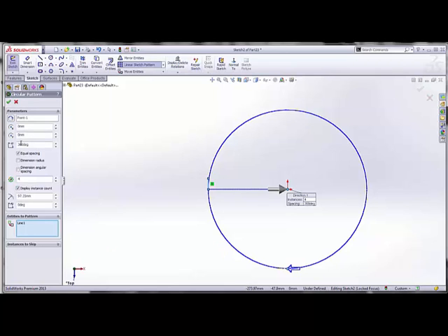As you can see, there is 360 degrees and 4 lines in a circular pattern, because this is the axis here, and they will be equally distant from it. You can change the clockwise or anti-clockwise direction. So you can change it. This is how it works.